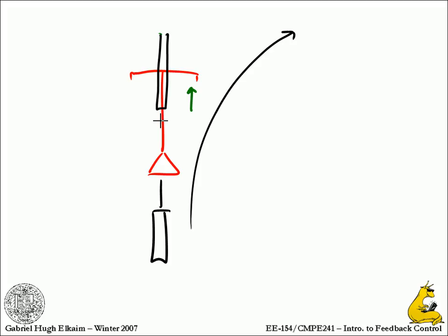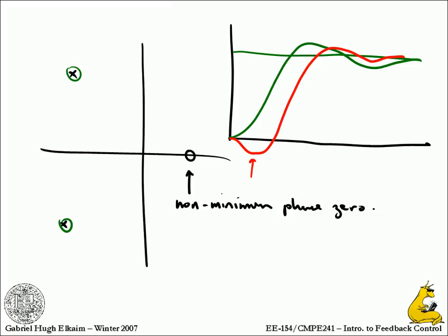They're unbelievable. Yeah, they've got actually metal plates. You'll see sparks coming off. And in fact, I know one guy who was complaining that on the Honda CBR the pegs for the rear bike stuck out too far, and as he would lean down in a turn, he actually took a grinder to it, because people would crash: as you lean down, the peg would hit the ground and lift the back wheel off the ground, and that's it. Once the back wheel comes up off the ground, you have no traction whatsoever, and the bike spins out. And so they would grind down the little peg so it wouldn't lift their wheel up. Anyway, all of that is to explain why.